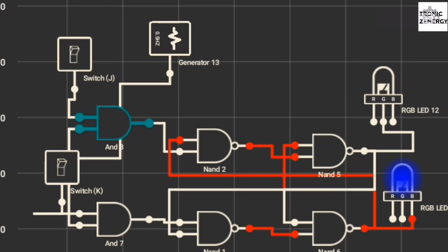It's going to turn off NAND gate number 2, because of the operation of a NAND gate: when both inputs are on, it's going to give you a 0 output. So since it's on now, when we turn on the other input, which is coming from this AND gate, it's going to turn off the input that it's feeding to this NAND gate. Once it turns it off, it's going to turn on, because this is turned off, because both the inputs are on. So that's why it's 0.